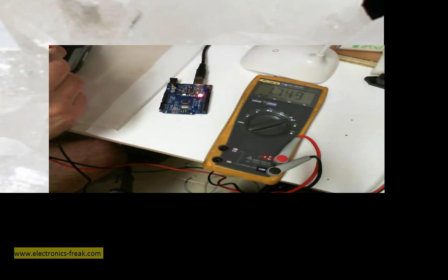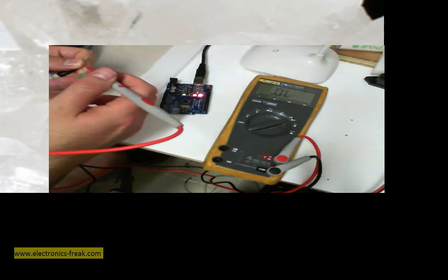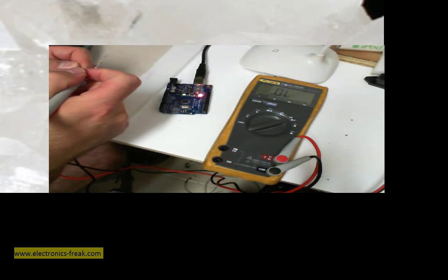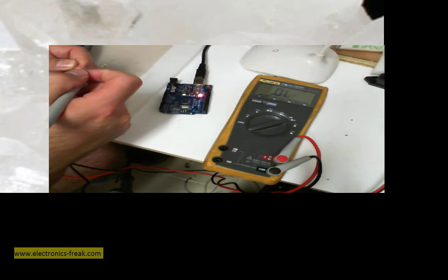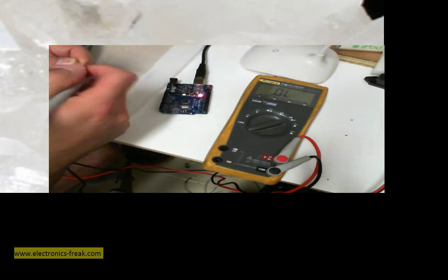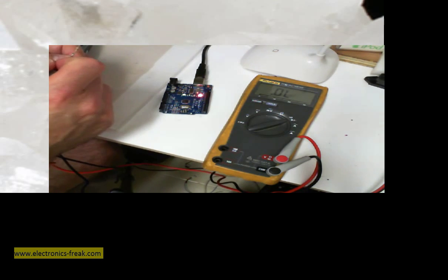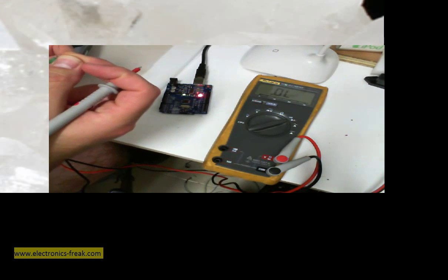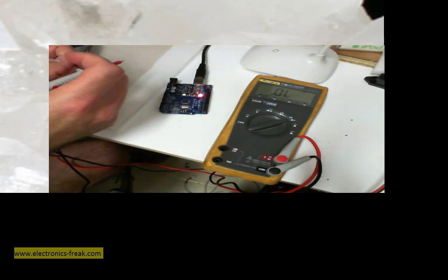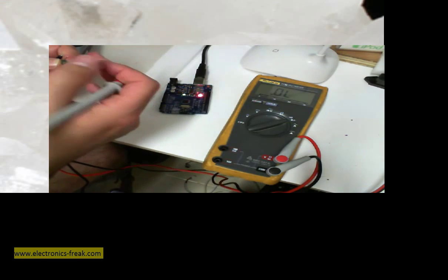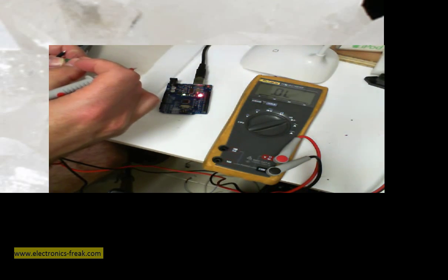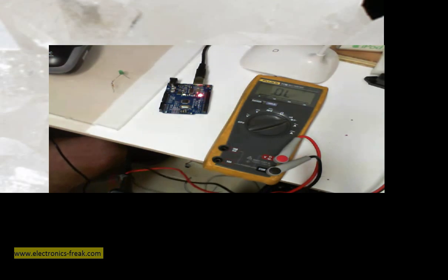We can see that if I put the red on this side and the black on the other, I have a reading. If I take the opposite way, it is open load, which means it is disconnected. So in this case that I can see something, I know that this side is the positive, which means it has to be the voltage that above 0, that is connected, let's say, to 5 volt, and the other side will be connected to the ground.